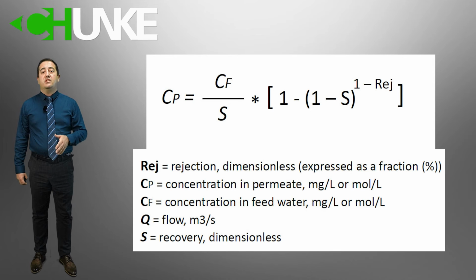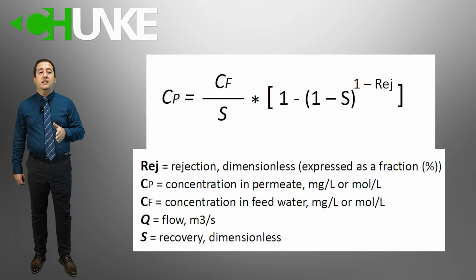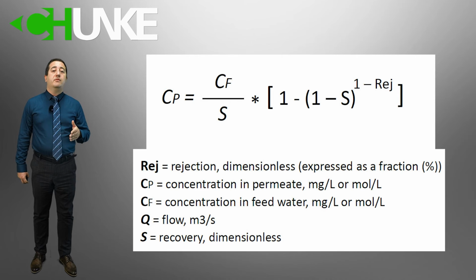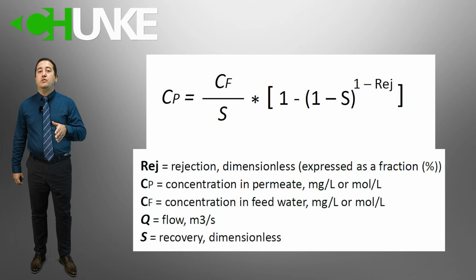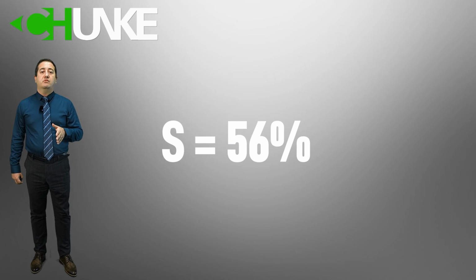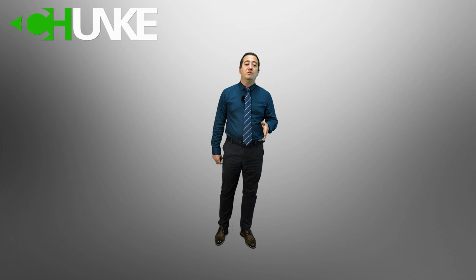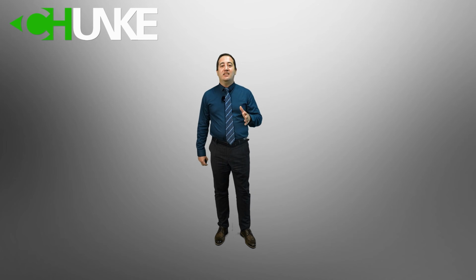For a brackish water system, the recovery rate is between 0.40 and 0.70. So we start with 0.45, 0.50, 0.55 and then we reach 0.56. It means a 56% recovery rate. If you want to understand how to solve it, you have to study a little bit of mathematics. Don't be afraid, it is not difficult.